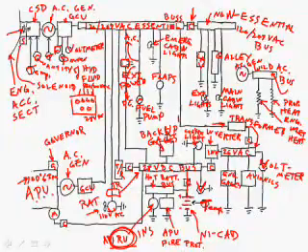But that's okay. If you feed the essential bus, you could, through a transformer rectifier, feed the 28 volt DC bus, and through an inverter run the 26 volt AC bus and run the engine gauges and the avionics for engine start. Heck, if the 28 volt DC bus is hot, you could charge the battery, and since a hot battery bus is hot all the time, you could start up the inertial navigation systems by powering it off of the external power. Or if all you had was DC, you could run just DC into the 28 volt DC bus. You could run anything on the hot battery bus through a contactor and an inverter. You could run anything off the 26 volt AC, and yeah, sure, you could run the engine gauges and the avionics for engine start. Wow.